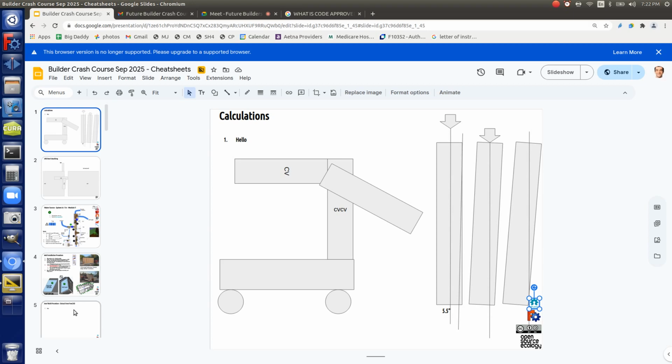Epoxy glues get up to the range of hard plastic, on the order of thousands of psi. So say you had really good super glue that's 1,000 psi and you're gluing the wood together, can you do that? And how much glue would you need theoretically to do it?